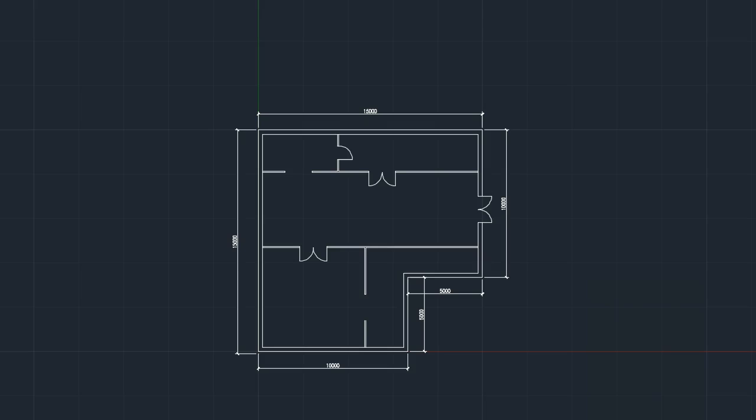The first stage in our building is to create the external walls. This is achieved using the offset command. This command is one of the most commonly used commands. It allows us to copy the line we pick and place it a specific distance away. For example, an external wall can be a certain thickness. In our building it's 290 millimeters.